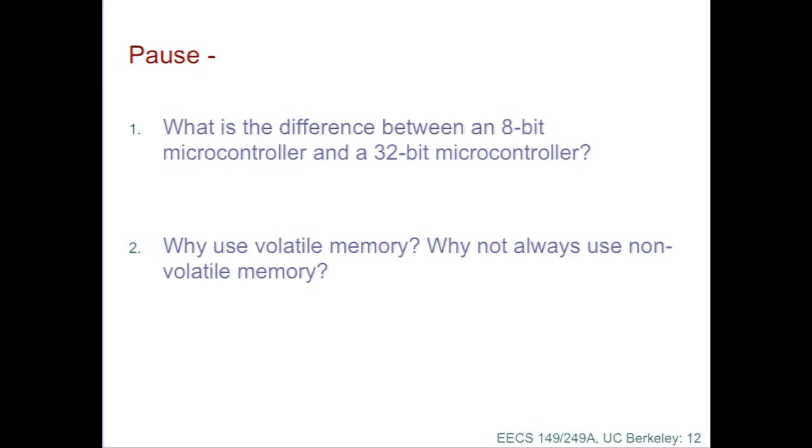Nope. Yes. The width of the data bus. It's the width of the data bus. It's how much, the size of the data words that you're dealing with in each instruction. Okay? That's just a convention, by the way. You know, we could have easily had a different convention where this processor would be called a 16-bit microcontroller because it uses 16-bit addresses. But instead, by convention, when we say it's an 8-bit microcontroller, we're talking about the chunks of data that it operates on, not the chunks of address.